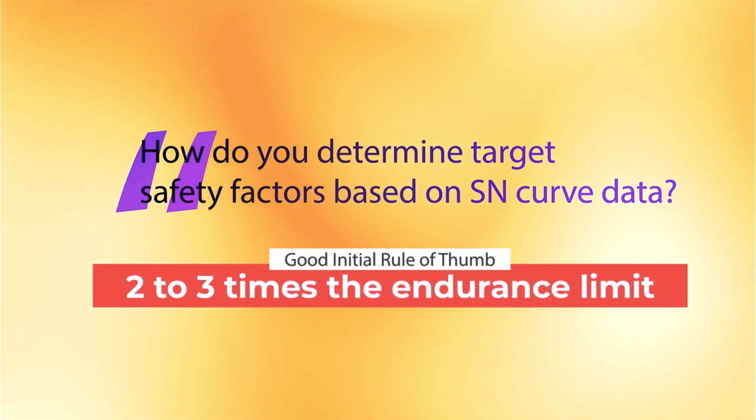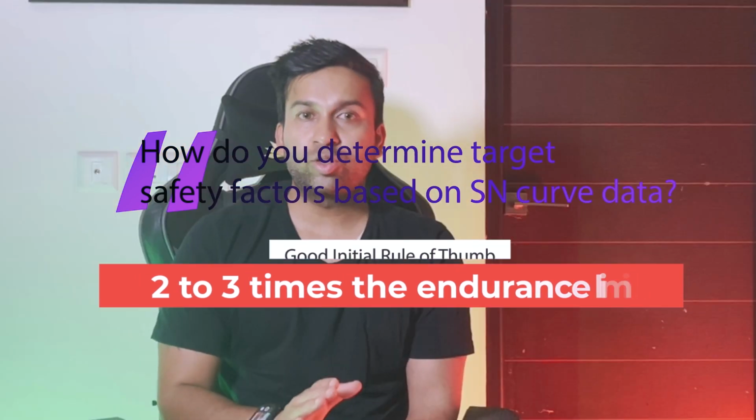While specific recommendations vary by industry and application, 2 to 3 times the endurance limit is a good general rule of thumb for initial design. Extensive physical testing should, however, follow.